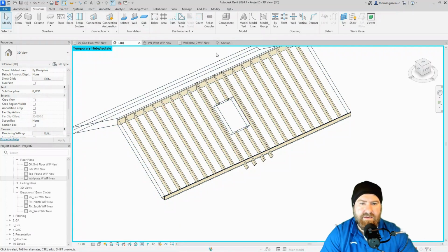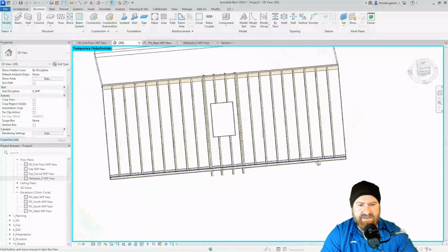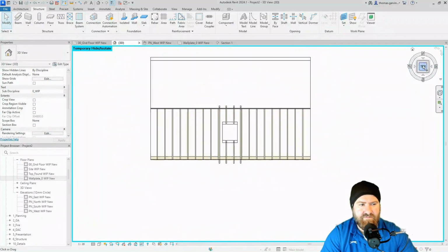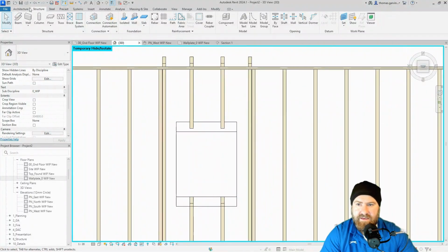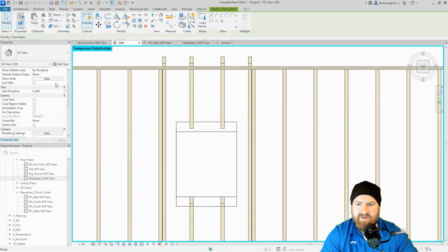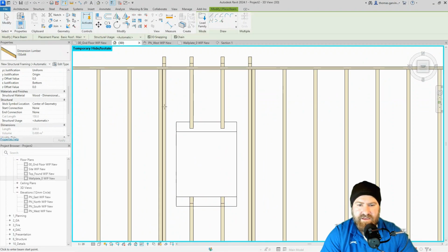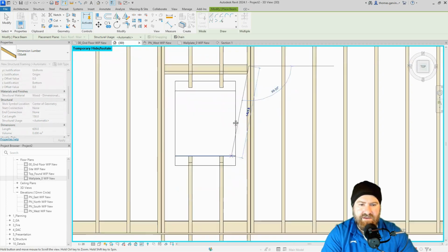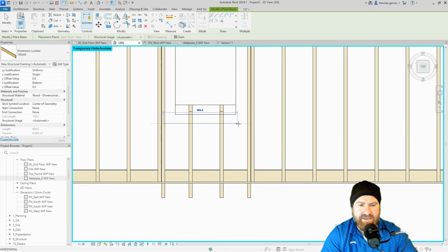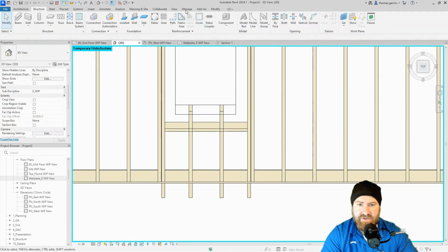Okay, and there we're good. I'm going to just rotate this a little bit and go to top view on the cube and go into structure, beam, user 150 by 44 again, and go from rafter to rafter. We can adjust the location afterwards and do it again over here, just below. Again, we can adjust the location after, okay? It's snapping to those supports, okay?